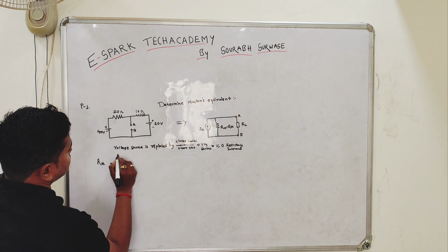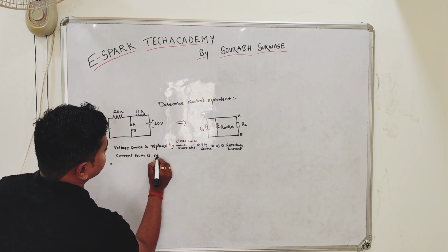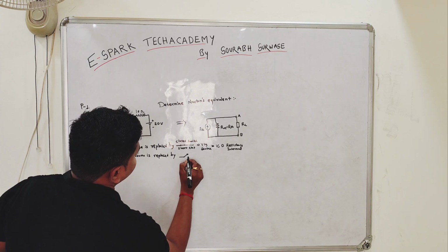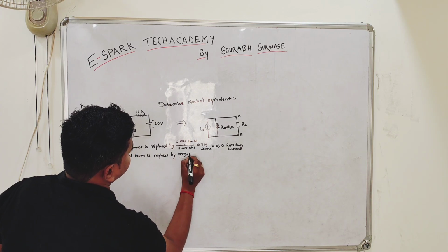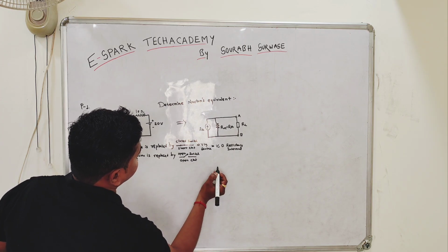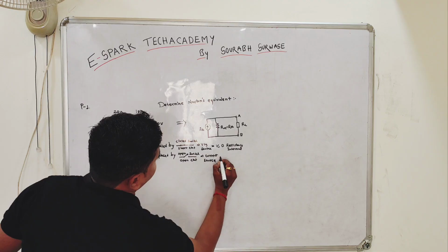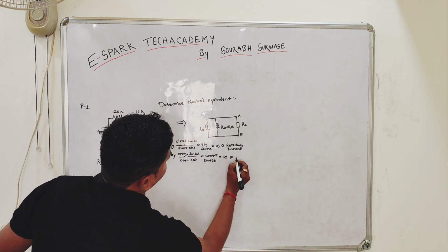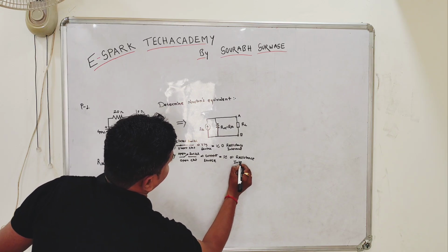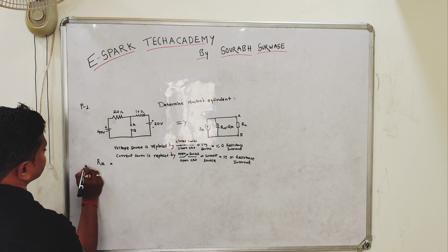And if there would be any kind of current source, it is replaced by an open switch, which is nothing but an open circuit, you can say, for a current source, and here it will be equal to infinity internal resistance. Now we have to calculate this RTH.